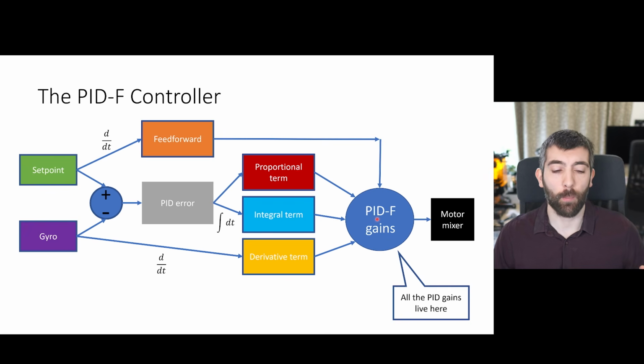That's the push that the flight controller is asking the quad to make on all three axes, roll, pitch and yaw. That is passed to the motor mixer, which turns that request into a change in throttle of all of the different motors. When this system works, it simply tries to minimize this PID error to as little as possible, so your quad follows what you're telling it to do with your sticks as closely as possible.